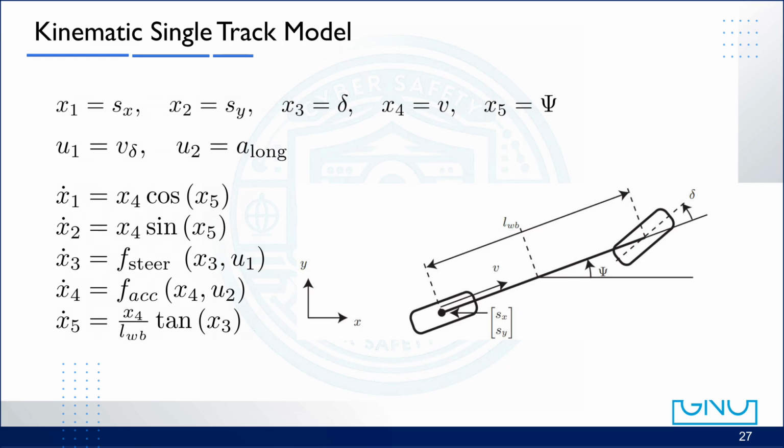So, these equations don't give the values directly, but rather describe how the state evolves over time as the vehicle moves. When we simulate this system, we integrate these equations step by step, predicting the next position, velocity, and heading. That's how dynamic models can capture continuous motion and produce realistic vehicle behavior. Even though this model looks simple, it is one of the most widely used in path tracking and motion control because it clearly connects geometry, steering, and vehicle motion.